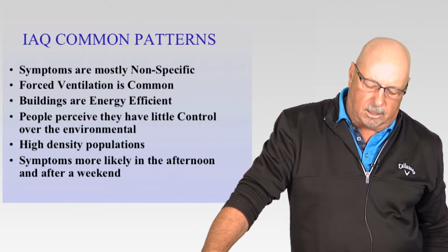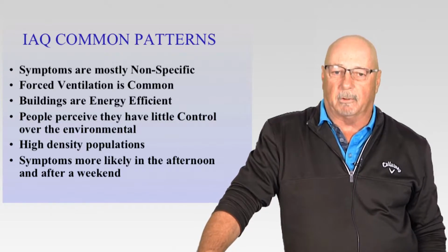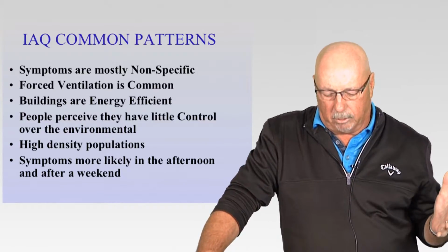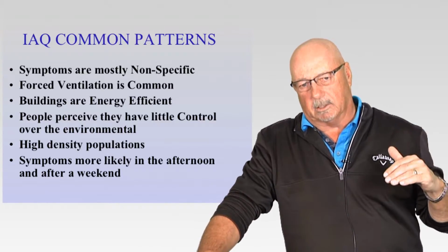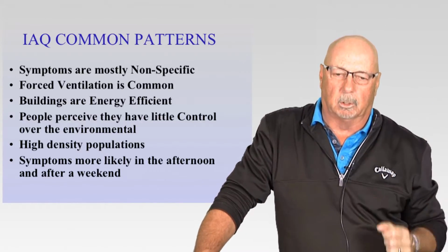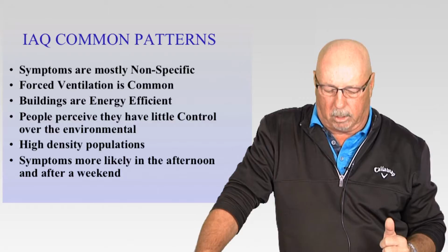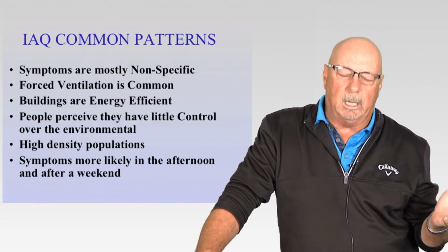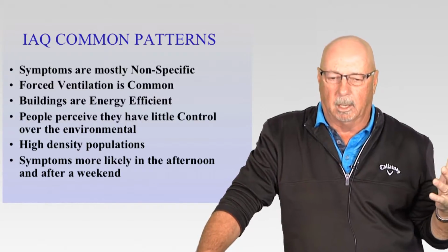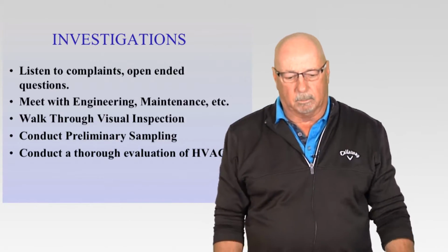And oftentimes we see that symptoms that do occur will either occur late in the afternoons or after a weekend break. In the late afternoons, it's because the contaminants that are being generated are building up through the course of the day, and so it's more noticeable in the latter part of the day because the concentrations of the contaminants are higher. With respect to after a weekend, people get out of the building and space and things clear up, and once they come back into the space on Mondays is when they start developing the problems again.